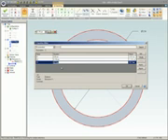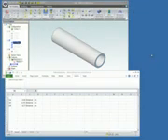Now we go over to the spreadsheet and set up the link to the sketch. First of all, a blank Excel spreadsheet is opened, named, and saved. In the interest of time, this spreadsheet has been opened, named, and saved with the parameter data already entered. Keep in mind that the cells with the values can only contain numbers. No other data can be in those cells. All that remains is to link the spreadsheet to the Libre part file.